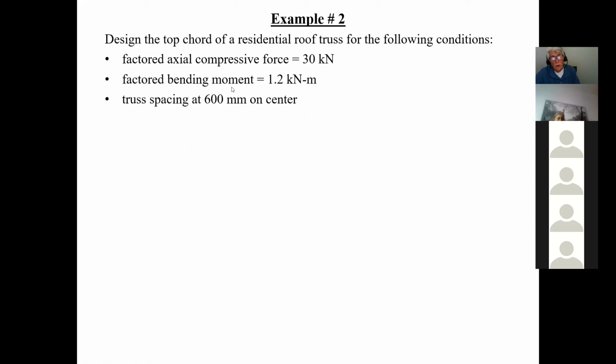Okay. The truss spacing is 600 millimeters on center, which is the typical spacing for roof trusses, guys. 2 feet is the typical spacing for roof trusses in Quebec. You can go less than 2 feet, but you shouldn't go over 2 feet. And like I said, 2 feet is a typical spacing.